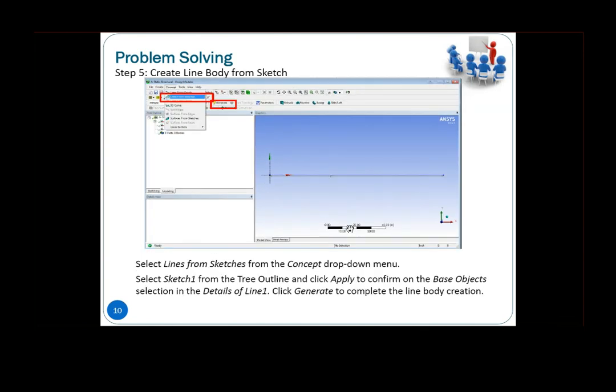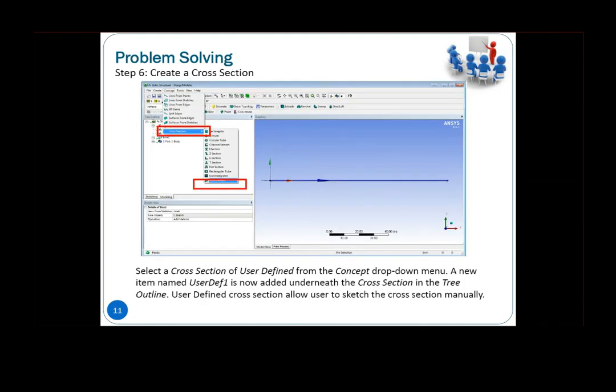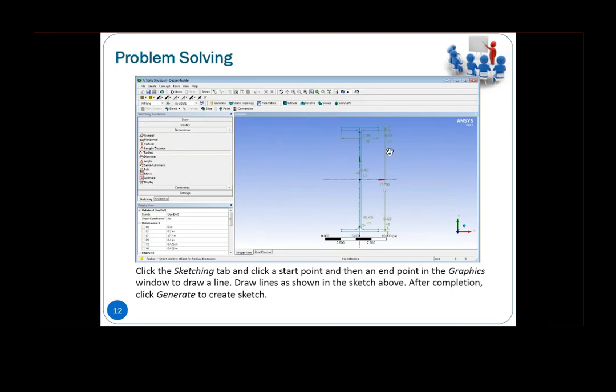Okay, then with its cross sections, here we are looking into user defined cross sections, or else you can use the I sections, but then you have to re-edit the dimensions, same as what I have provided to you just now, right? Or you find from the internet the link that I have shared with you. Okay, so we draw the dimensions accordingly.